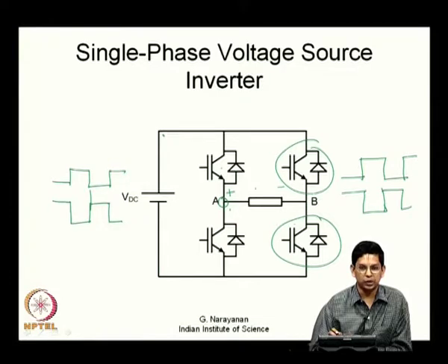they do not actually, but we will ignore the switching transitions for the time being, we deal with them as ideal devices. So, ideal devices do not drop any voltage when they are on, do not conduct any current when they are off, and their switching transitions are instantaneous. These are the attributes of ideal switches, and let us regard all these switches as ideal now.